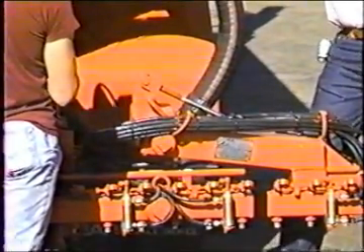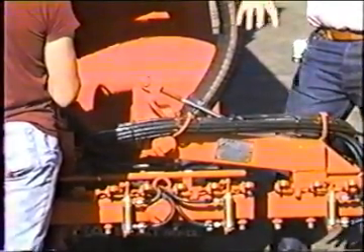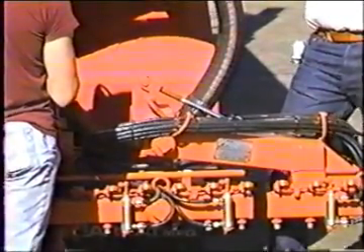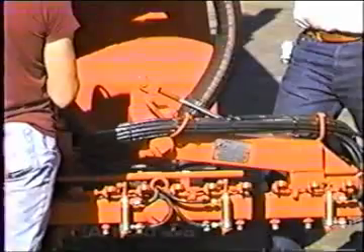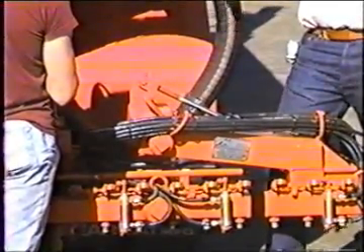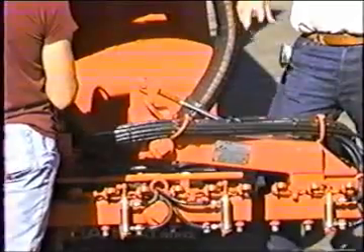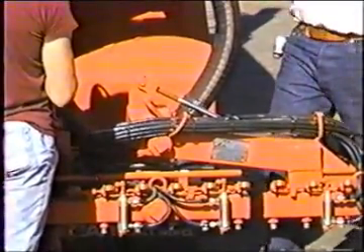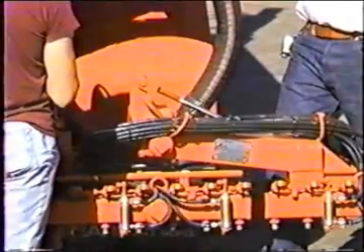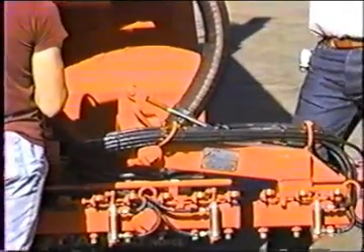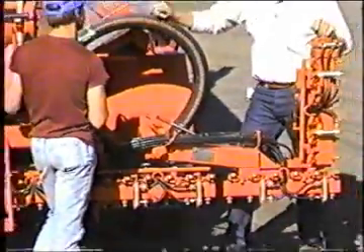Well, obviously if any of that material gets in a passage and cools off, then we're plugged up. So everything on the machine is full circulating. That is, when we're not spraying and we have the material in the spray bar or the piping system, it's moving through it. It's circulating entirely through it back into the tank so that everything stays hot and will immediately spray when we turn it on.